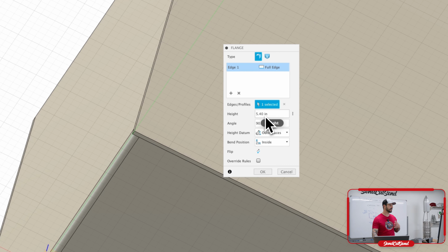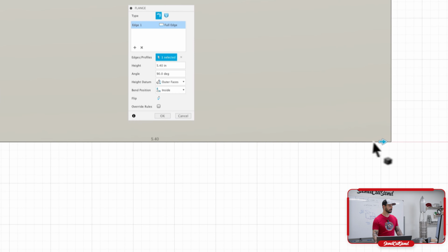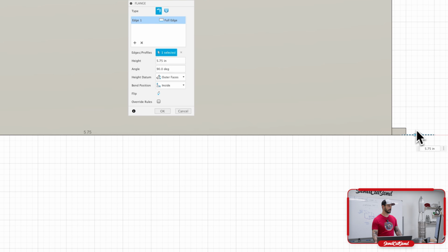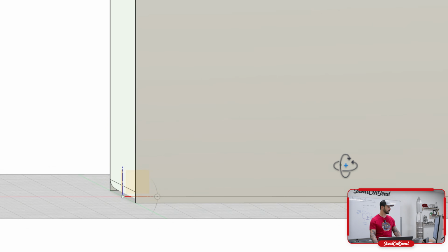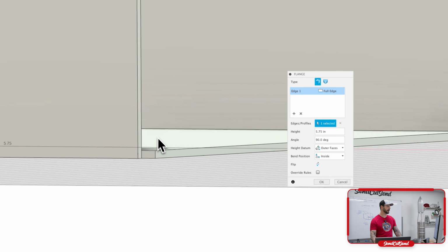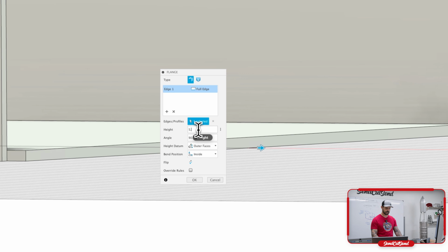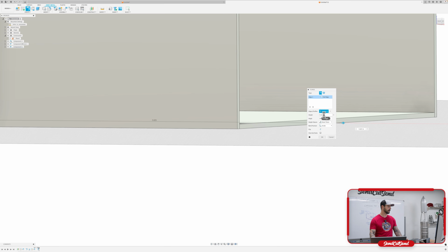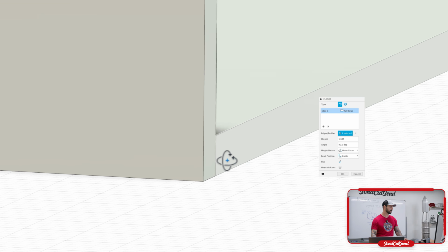And so we have a handful of different dimensions and characters that we can play with here. I'm going to roll up on the side here, and we can see that my part ends up sticking out the end of it. If I look, my measurement is on the outer face, so it's from here to the end of the flange, as I have it currently selected. So if I type in 5.625, you can see that it ends up coming out completely flush on the end.